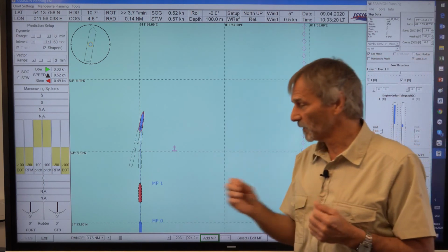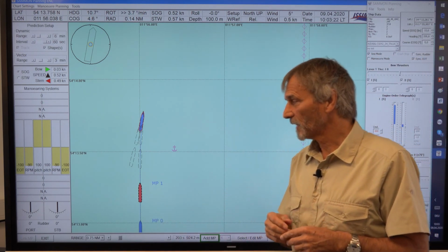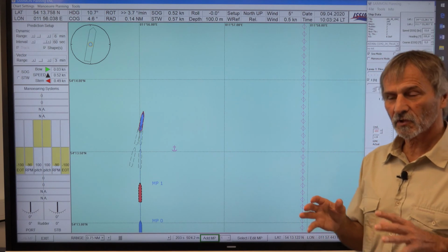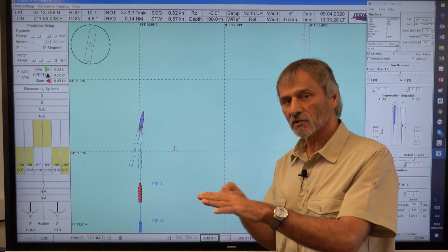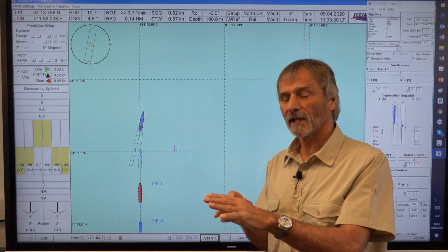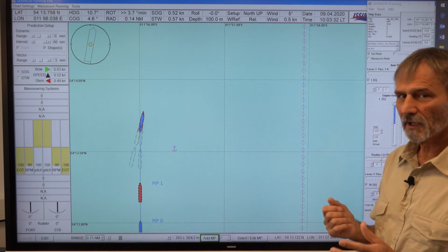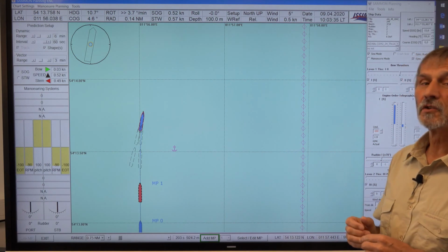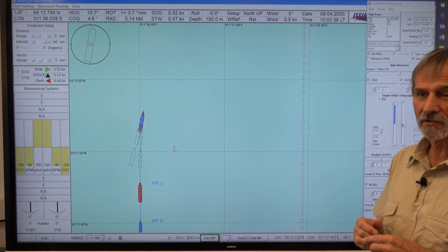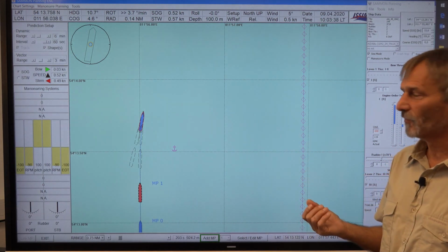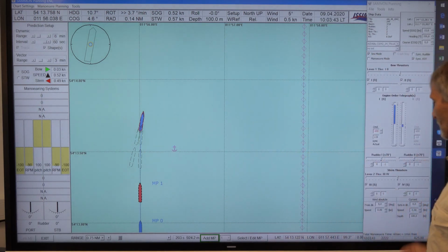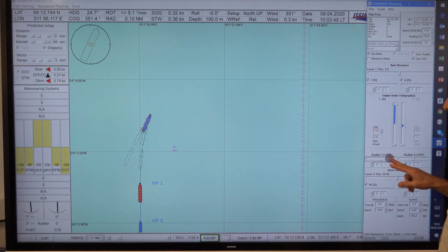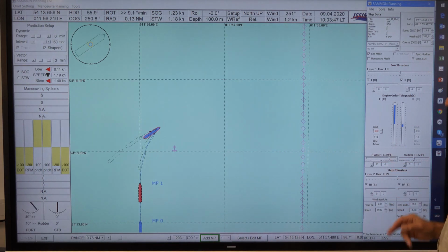And the fifth measure was that in case we have a twin screw vessel, we can already operate one engine astern. Then you are well aware if you have to stop all of a sudden, then you can shorten your stopping distance. And maybe you could even combine all of these parts, even to this one, that we use the rudders to further reduce our stopping distance.